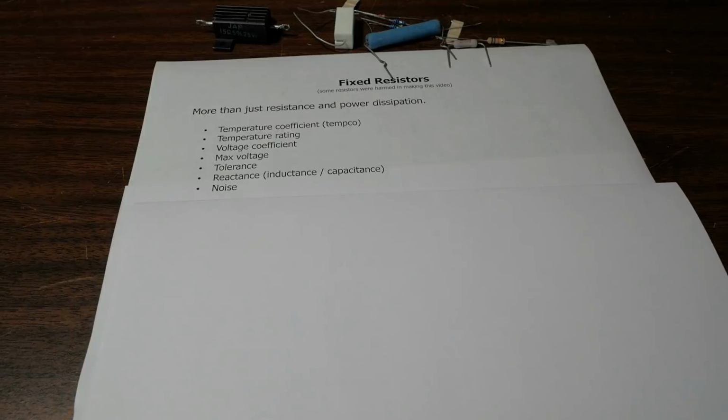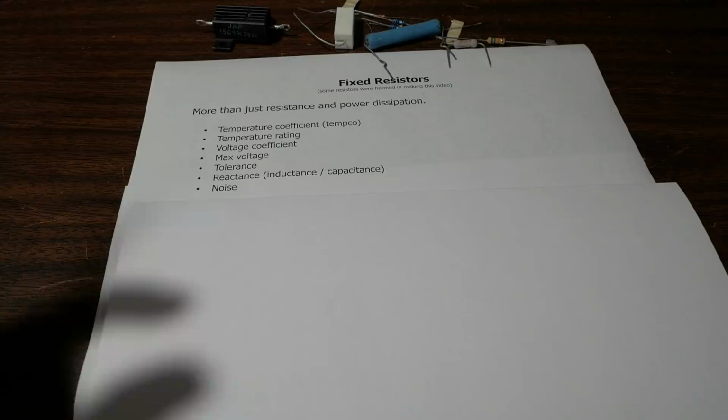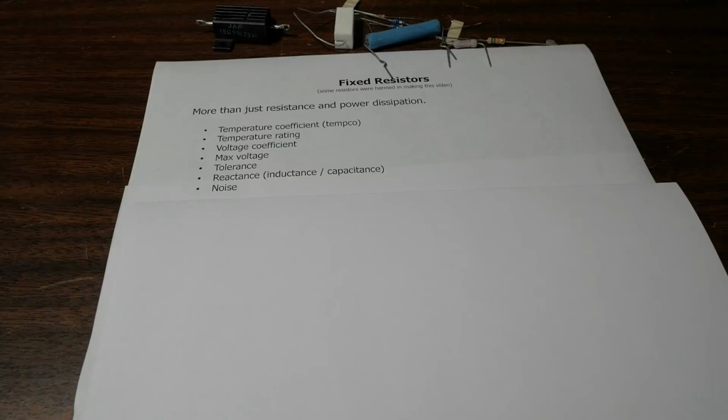One thing you can do to remedy that is put several resistors in series. For example, if you have one 100K resistor and you're having an issue where the voltage is too high, you're exceeding its maximum voltage with a train of pulses or whatever in your circuit, you can take 5 20K resistors and put them in series, so you are actually making that distance larger.